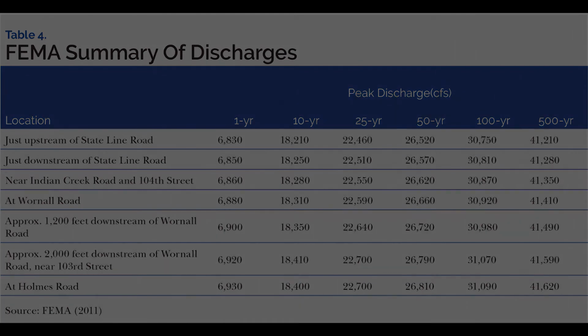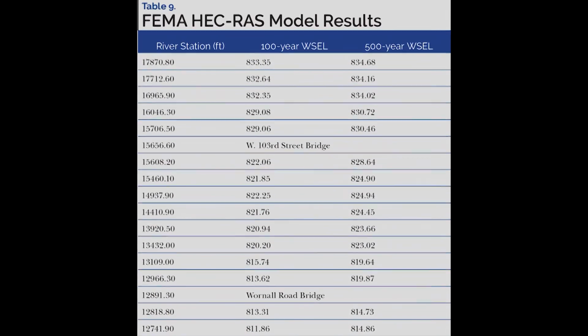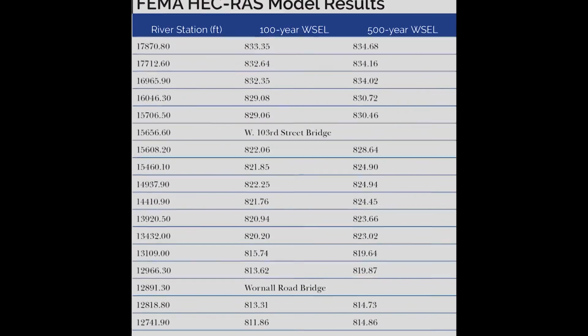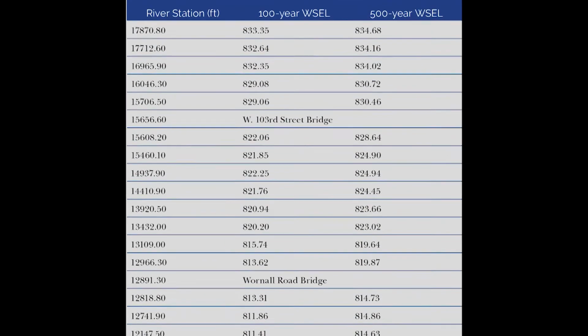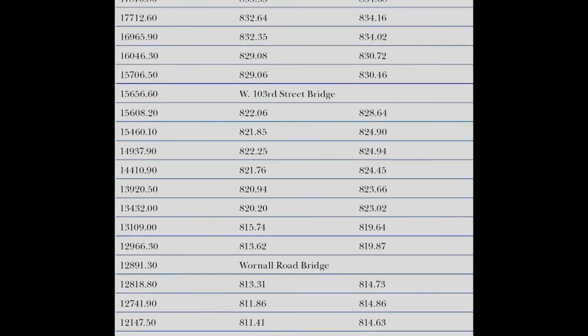And so once we understand hydrology, we understand what flow rates we have available to us, what we're actually modeling. Then we begin to actually start creating that initial physical model. Before doing that, we do run and take the information from typically a one-dimensional model that exists, in this particular case, the FEMA model. While it did not accurately depict the flood extents, there's still valuable hydraulic information in there that we can use for our physical model.